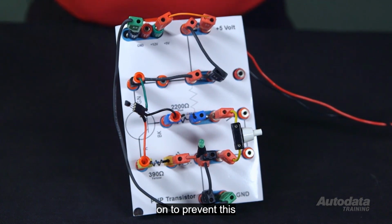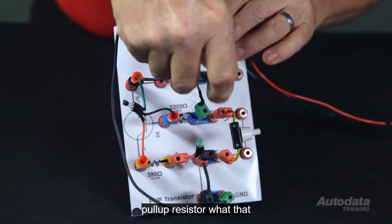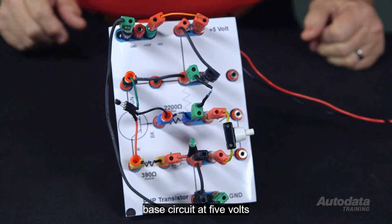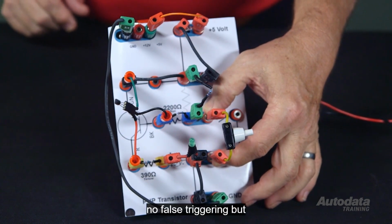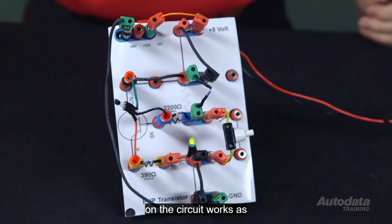To prevent this, we can put in a pull-up resistor. What that does is it holds the base circuit at 5 volts until the switch is turned on. Put my fingers on it again, this time, no false triggering. But if I turn the switch on, the circuit works as it normally should.